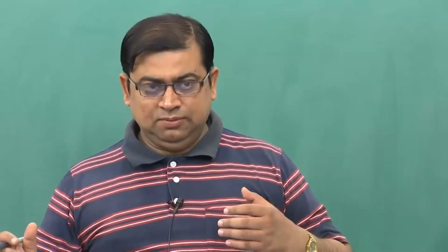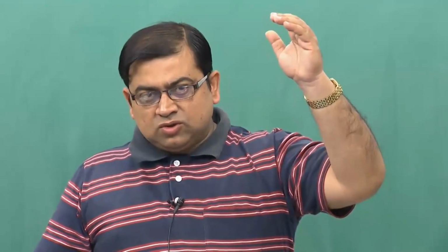Okay, so in order of RPN you now analyze the problems, and the goal is that you should start eliminating at least the first 3 or 4 problems to a totality, and then study the level at which the problem gets resolved or sorted out, and then study the next 3 or next 4. So you should not spread yourself across all of them, but study maybe the first 3 or 4 RPNs or the potential failures and eliminate them, and then go to the next ones.